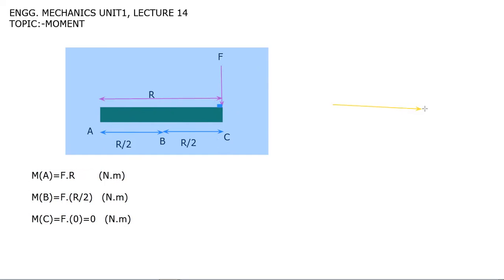In the case of the door also, we have seen that as you increase this distance, the action at the hinge increases, right? This is your door, and you increase this distance. You are applying the force here, and as you increase this distance, the moment acting at this hinge also increases. So moment has a natural significance, remember this thing.